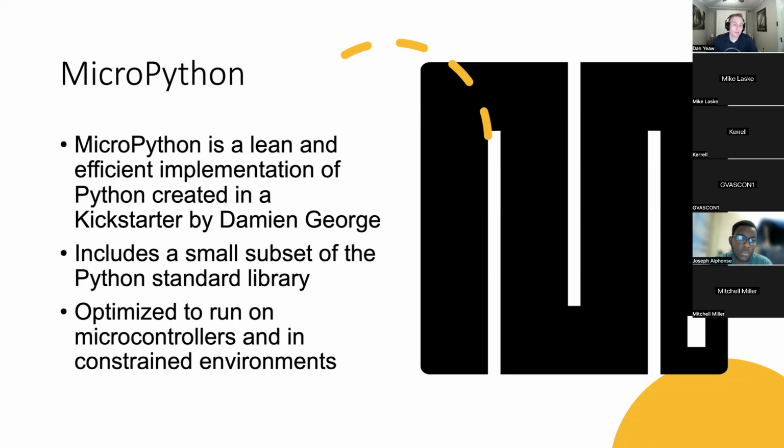This allows MicroPython to run as C on a microcontroller, and then allow you to use Python directly on it, including the REPL environment that you're used to with your normal programming, and not having to compile code and all that type of stuff. So you can write Python directly onto your embedded system now.